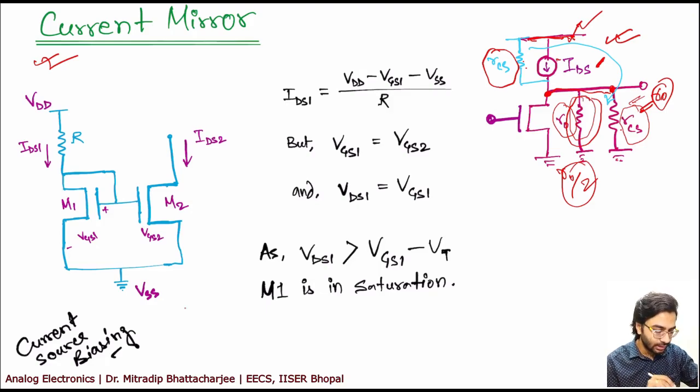Now if you see this particular biasing or circuit, there are two transistors used. And why is it called current mirror? Because we used a current biasing on this side, and the value of current is a biasing, right? So we need a control over the biasing. It's not like something fixed or something we do not have control over. Generally we need a control on the biasing at least, because that is where we fix our values. This IDS value is very important, because it is going to decide my gm value, beta value, everything.